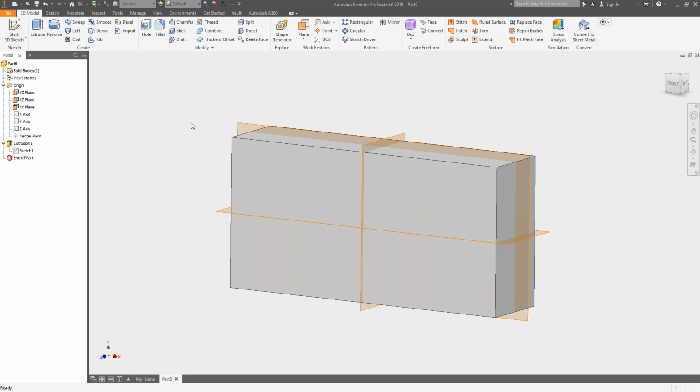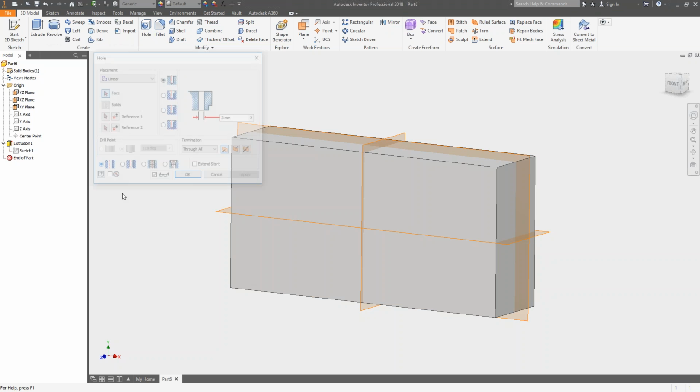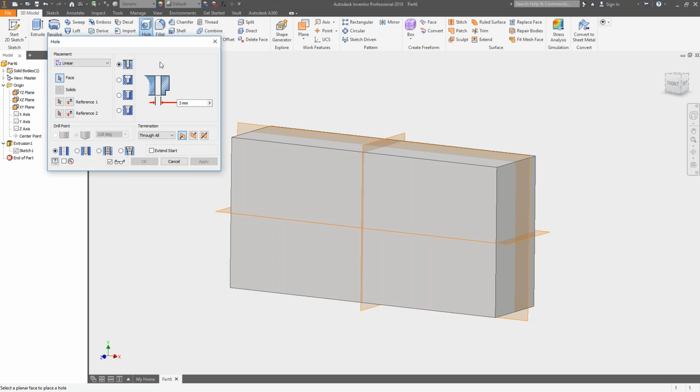So the rule of thumb, if there's a 3D feature that allows you to create that particular piece of geometry, use the feature rather than the sketch. So for instance, that hole I wanted there, I would issue the hole command, and this is an intelligent hole command. It's not just a circular extrusion, because we can do things like making it countersink, spot face, counter bore. We can add threads to these, whatever we want to do. But I'm going to place the hole on that face.